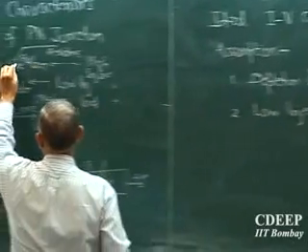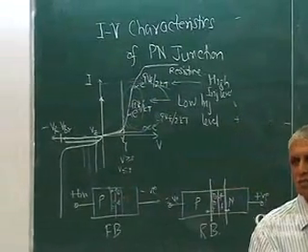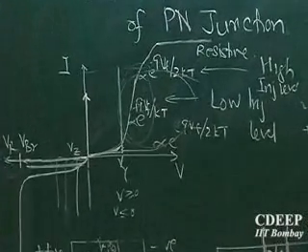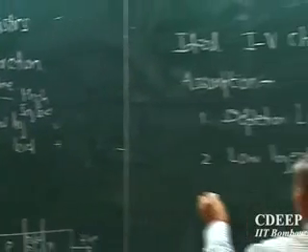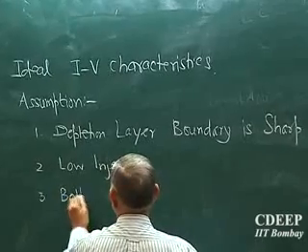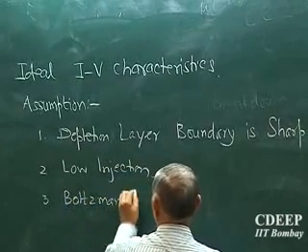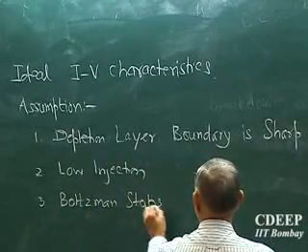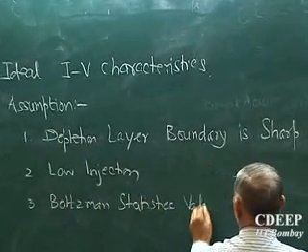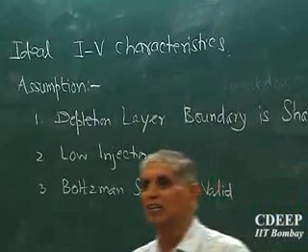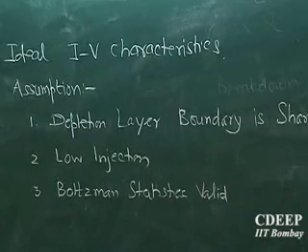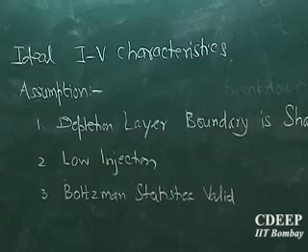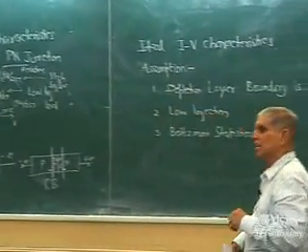That's what we are looking at, low injection. The first theory is for e^(qV/kT) minus 1, fine. So let's see this. Then we assume, which is not correct every time, that Boltzmann statistics is valid. In non-equilibrium, we have said Boltzmann statistics is not valid. But how did we allow it to happen? Using quasi-Fermi levels. We said, okay, we'll still use it. So that essentially means we'll use quasi-Fermi levels in steady states.